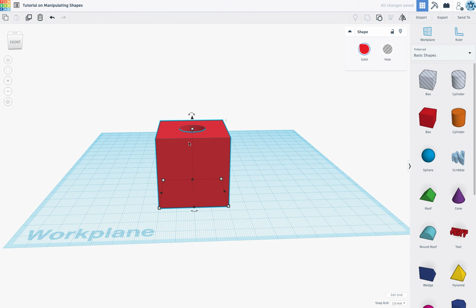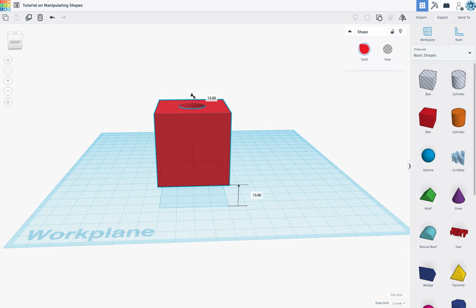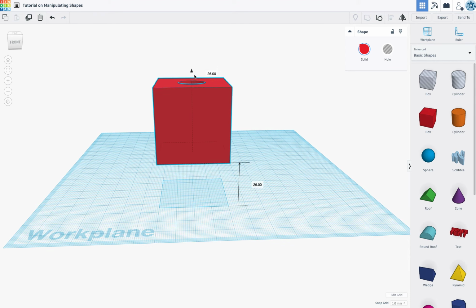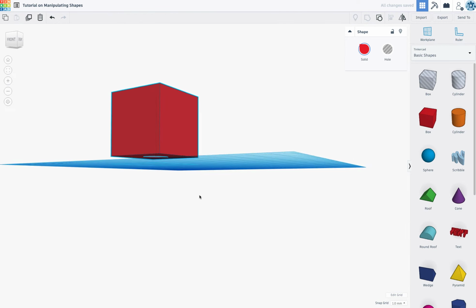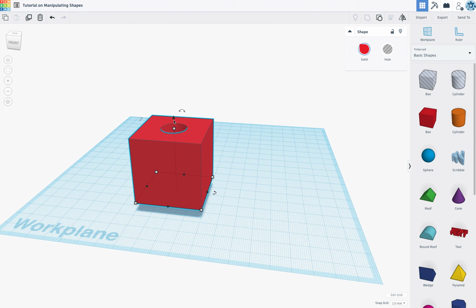And then what we could do is, there's a cylinder, this cone. If you want to lift it up, it goes this way, and that will restrict you actually from going up and down, and it'll tell you what the height is off of the base plate. Okay, so that was 5 units up for 5 millimeters, and this is now 0, and you can also go negative.